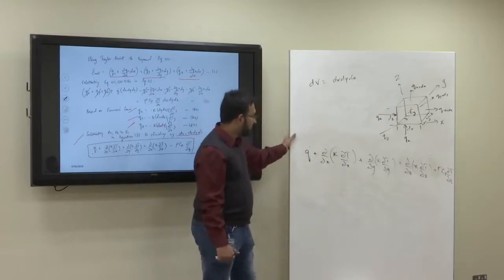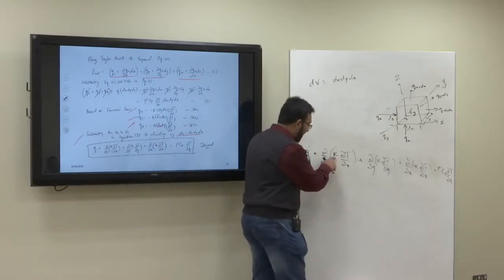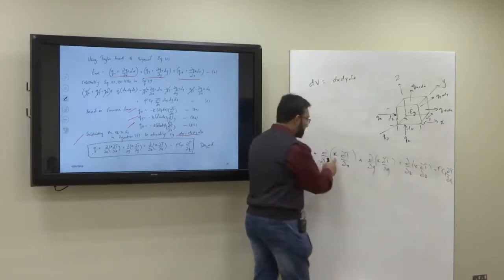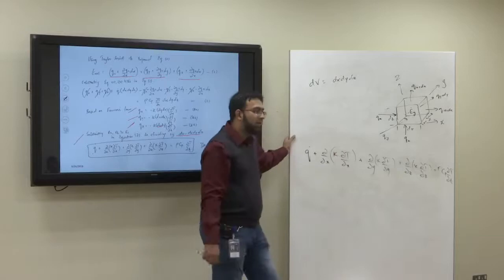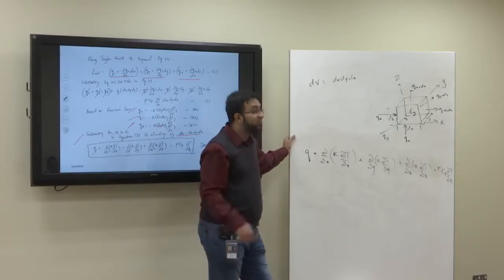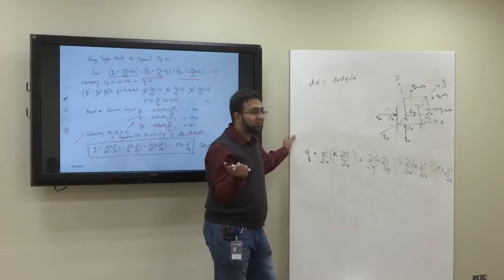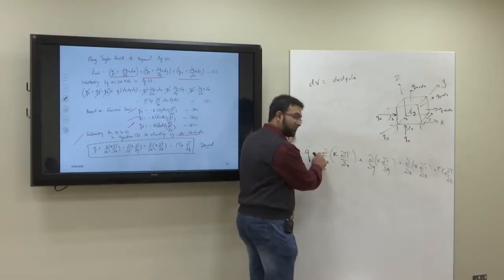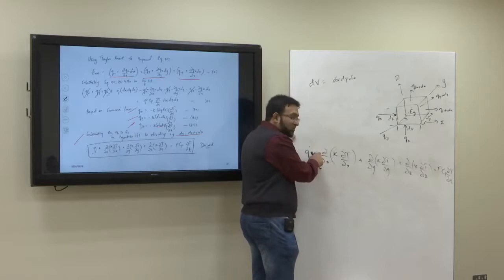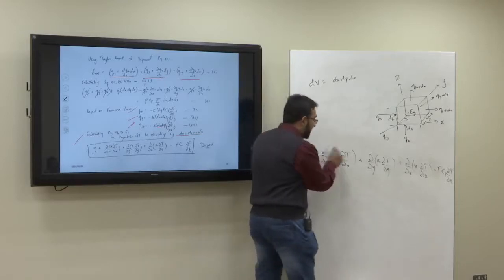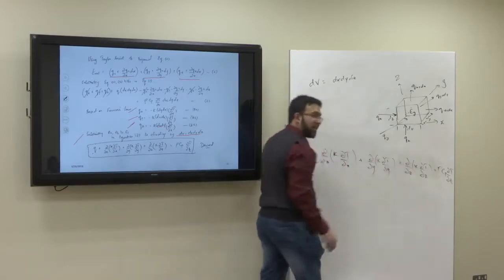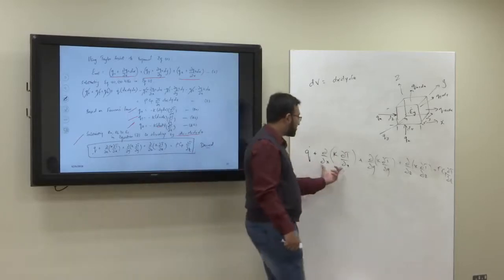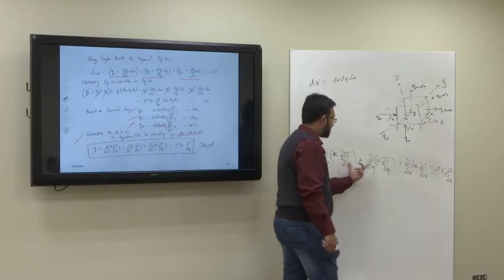You see here K is inside these brackets. So that means K could be dependent upon direction. But if the material is isotropic, K will come out of all the brackets, because K then doesn't depend upon x, y, or z. Okay, this is for heat transfer in 3 dimensions, in x, y, z.